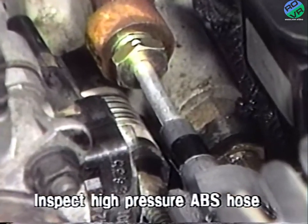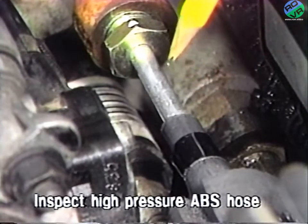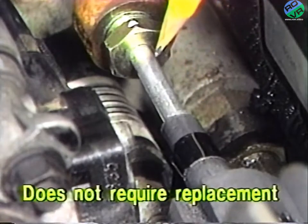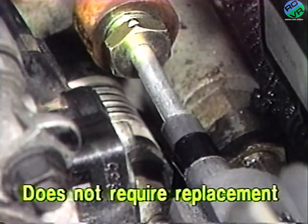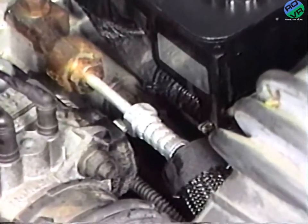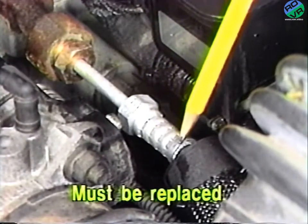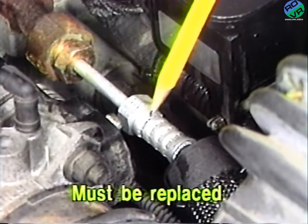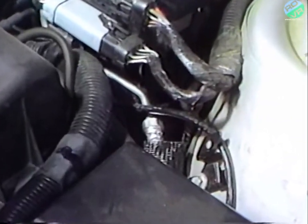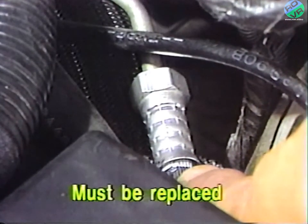To check the hose, look at the hose end fitting at the hydraulic assembly. If the hose to fitting end has a formed end, as seen in this example, the hose has already been replaced and does not require replacement again. However, if the hose to fitting end has a crimped end, as seen here, the high-pressure hose must be replaced with the applicable recall service package. On BB body vehicles, the hose to fitting end is located close to the hose mounting bracket on the left shock tower.